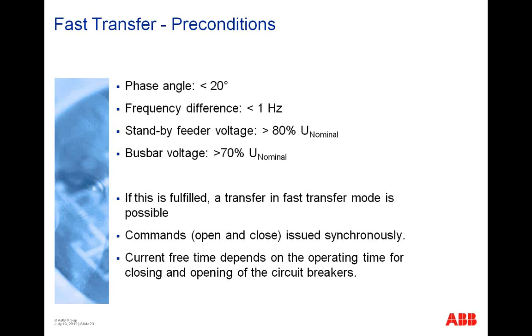At this moment, we have a kind of synchronous conditions for a fast transfer mode. And only in fast transfer mode, if these conditions are given, we send the commands to the main feeder breaker and to the standby feeder breaker at the same time, synchronously, but only in fast transfer mode.